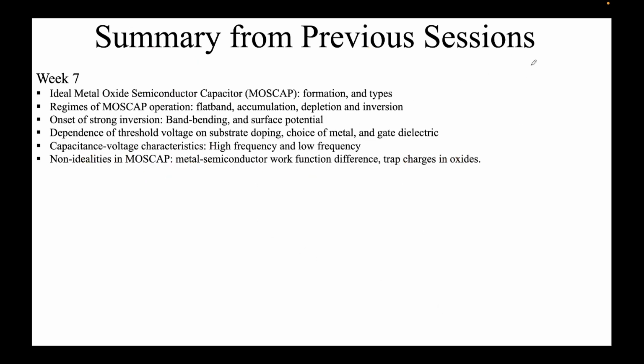And then we saw another device, the MOSFET. Here we have the metal, then the oxide, and finally the semiconductor, which we usually grounded. The metal is also called the gate. Let's say this is a p-type semiconductor. If you apply a positive potential, you will attract electrons at this interface, which is called accumulation. If you apply some negative potential, you will repel the holes, essentially creating a depletion region.